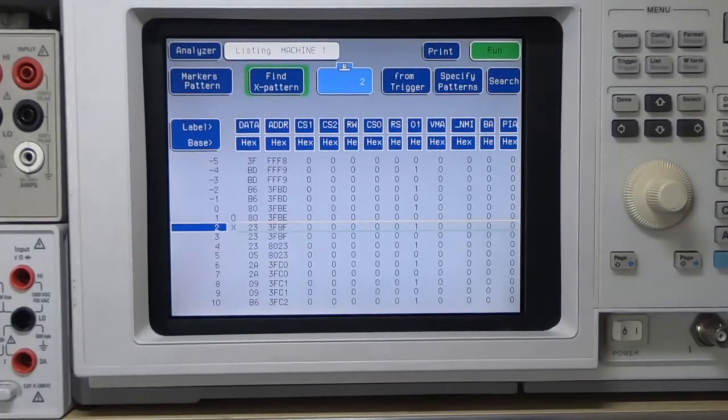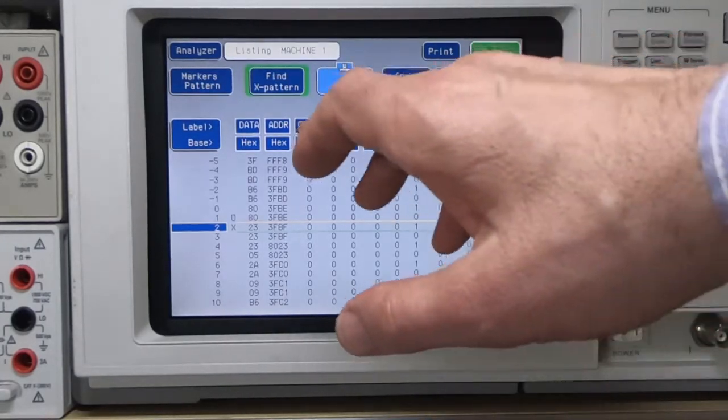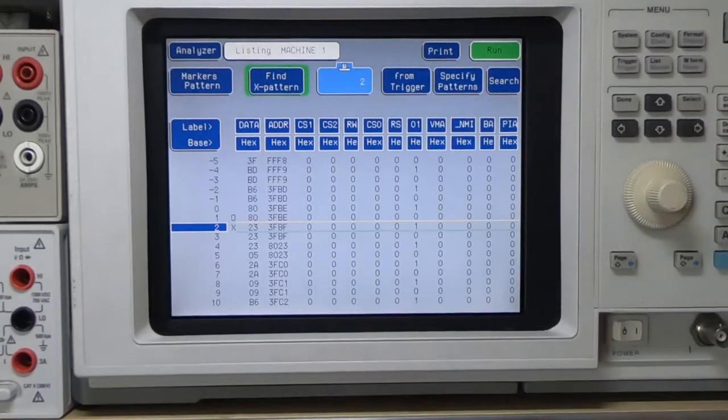What the inverse assembler allows you to do is essentially give labels to all the known addresses. So for example, if it's a port value, then whenever that port value is accessed with an in or out instruction, then the reverse assembler will put that into the list view, telling you that you've accessed port A, port B, or whatever name you've given to it.